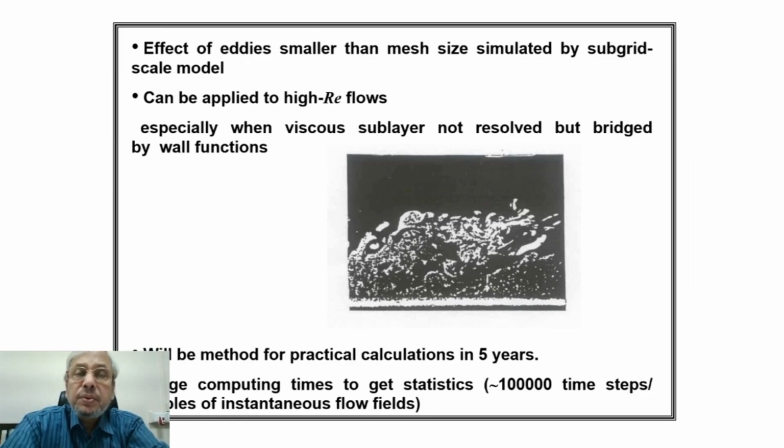So grid resolution, or the fineness of grid, the requirement is not as much as direct numerical simulation, but here also grid size has to be quite small, and usually for laminar flows, when you go for grid independence test and all, by reducing the grid size, increasing the grid numbers, for large eddy simulation techniques, definitely we need much larger grids than those type of grid requirements.